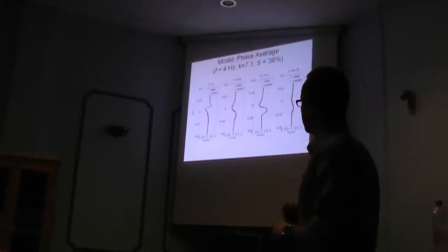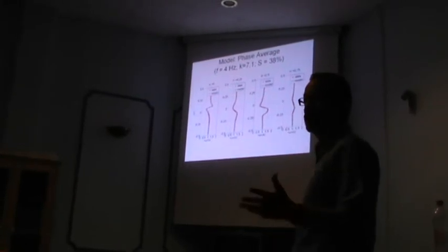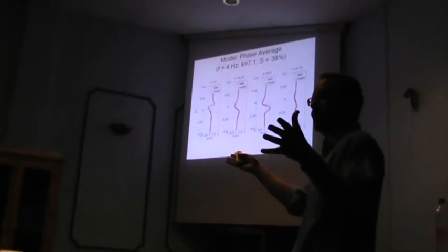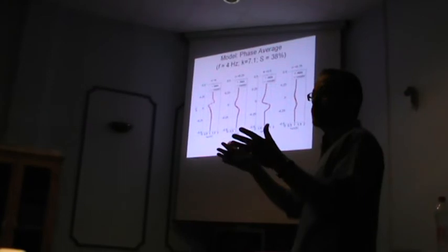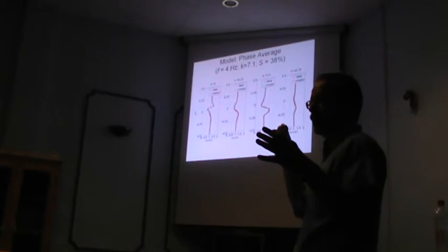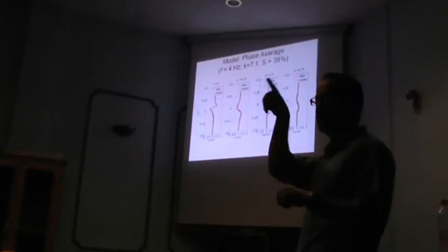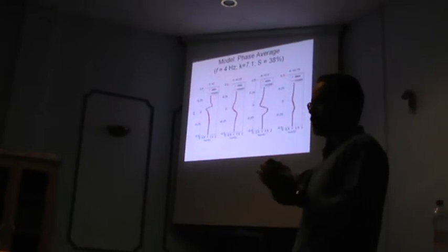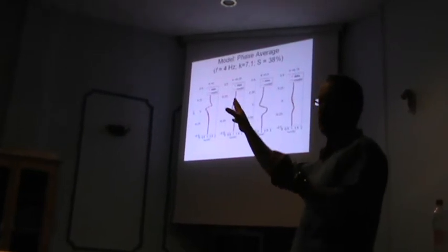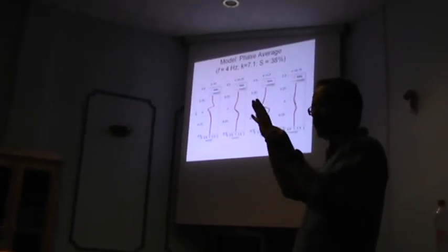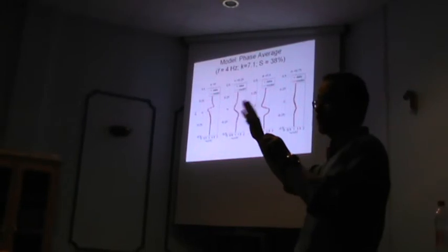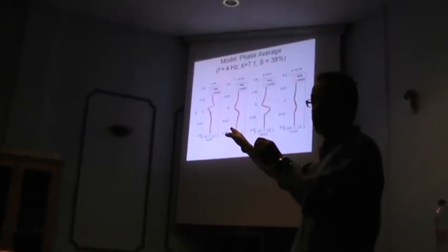And this is the agreement that you get, which is still quite good, especially given that you're making an assumption that the pattern stays the same. The reason for this is the Biot-Savart relation that we looked at. If you notice, in the denominator of this relation there is a division by the distance cubed between where the vorticity is and where you're calculating the velocity. So the effect of faraway vortex structure decays fast enough that it's not that important that you duplicate it exactly.